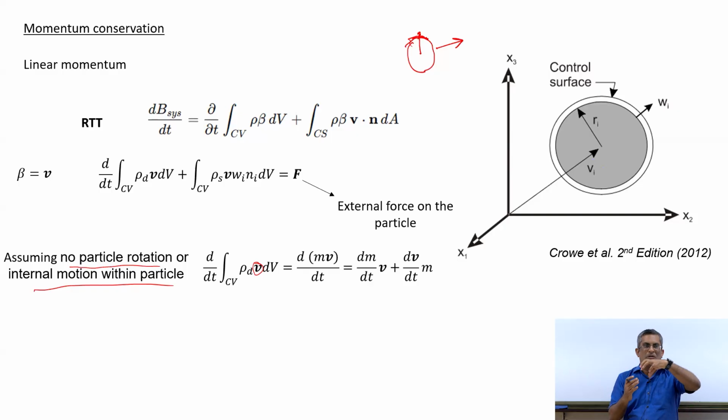The liquid which has higher vapor pressure would tend to move towards the interface, leaving behind the one which has lower vapor pressure. This also can cause some velocity, though the magnitude depends on the particular case. It may be much lower than the translational velocity of the particle.